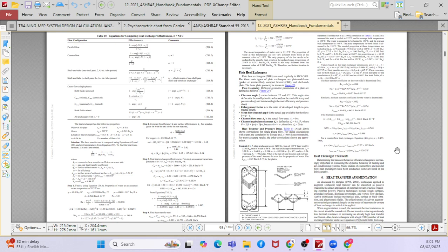See, as a consultant, we are not depending upon the equations. The equation is for getting the design values. But whenever you go with the final IFC package, you always have to refer to the manufacturer. Finally, what we generally do is calculate it, then send it to the manufacturer for their selection, because sometimes they ask for the noise level and all these things. We are deciding, we are sending, we need this heat recovery, we need this preheat pipe. But you are saying you will send to the manufacturer and take their advice.